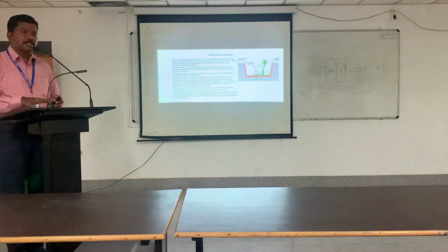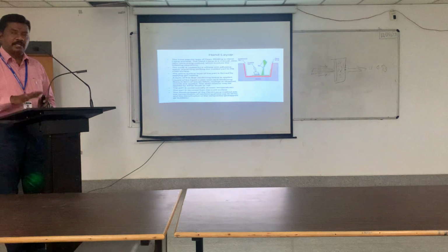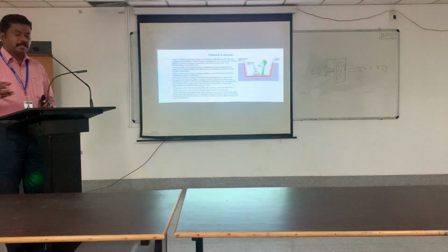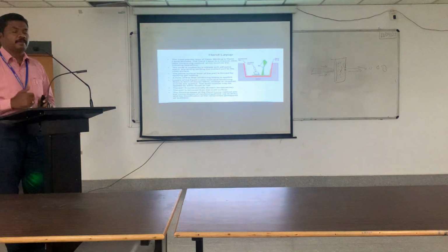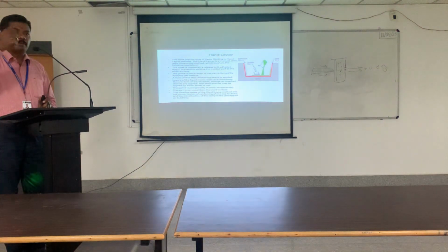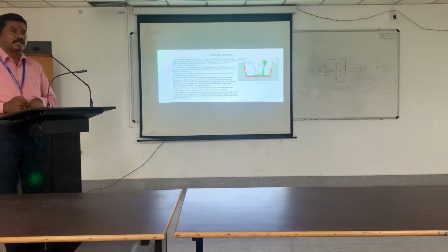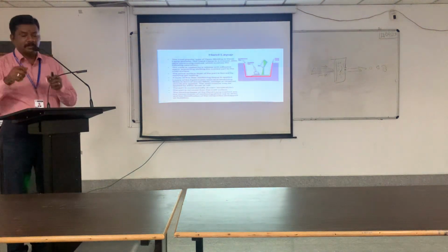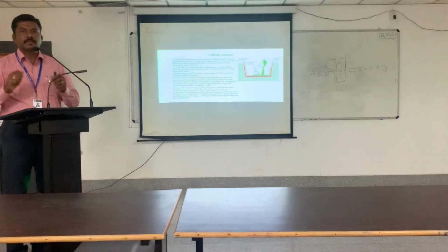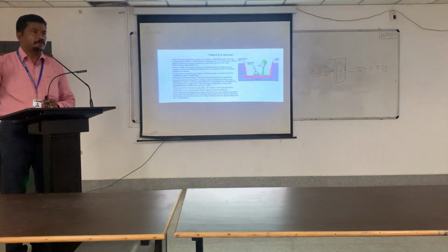Okay. If it is atmospheric cured, then you can leave it for either 5 hours or 10 hours, depending on the curing system of the matrix material selected. And after 10 hours, you can remove the top plate and you can peel off the OHP sheet, that is the non-sticky film. Then the laminate can be taken. Bottom side also you can peel off the OHP sheet. Then finally the laminate will be ready.